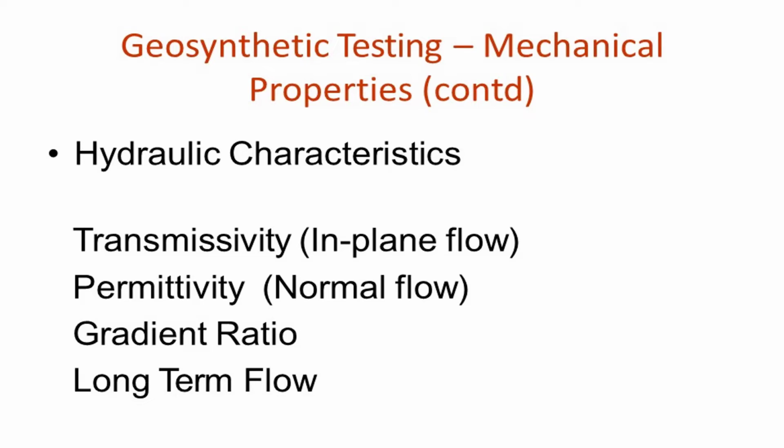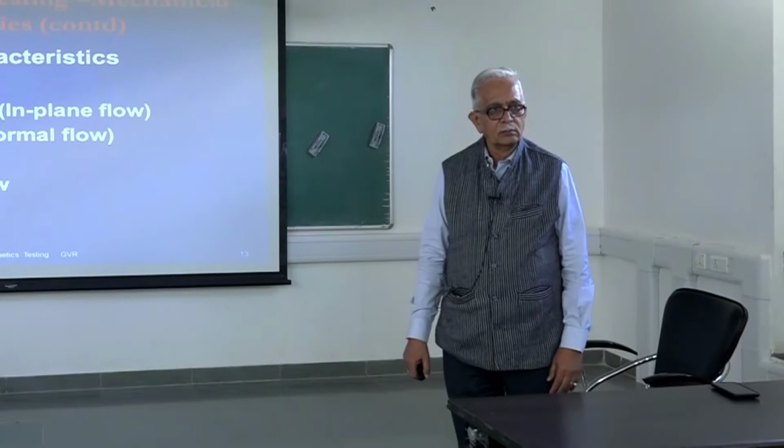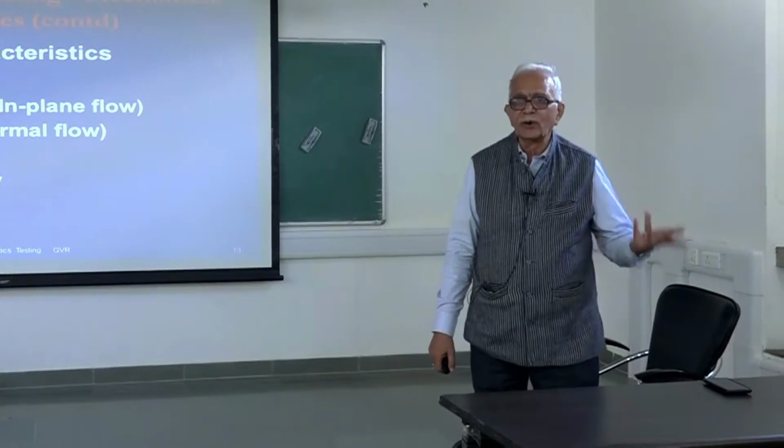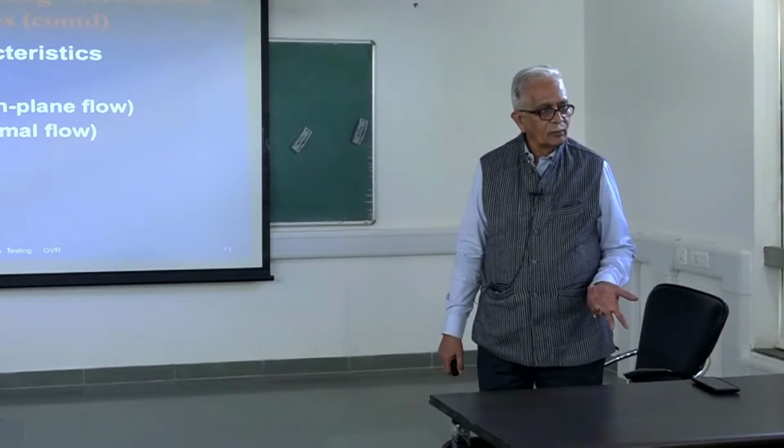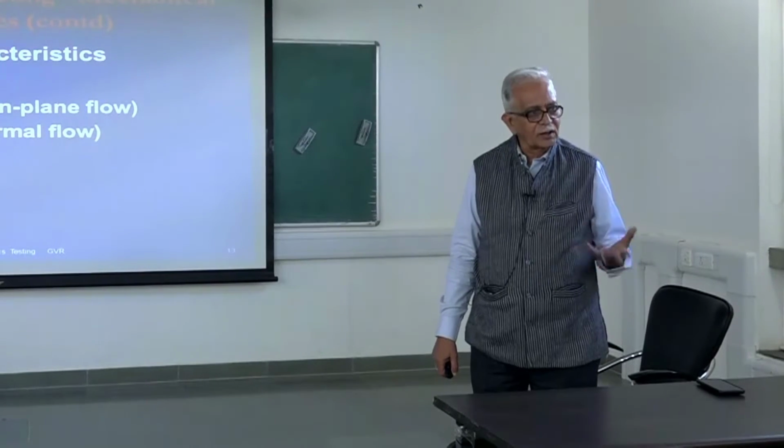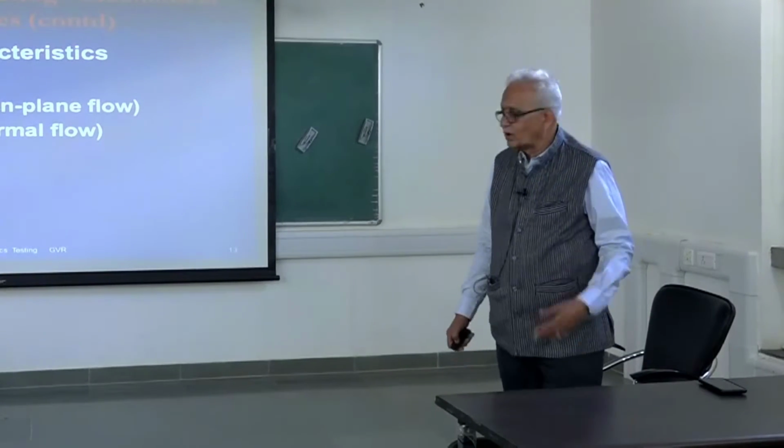Then of course, the other direction we are going to use for filtration characteristics usually is really the normal flow, and that definition, again divided by thickness, is going to be called permittivity. This is a typical flow characteristic. It's like a permittivity coefficient. Okay, permittivity coefficient multiplied by thickness or divided by thickness is going to come out later. We will see that clearly.